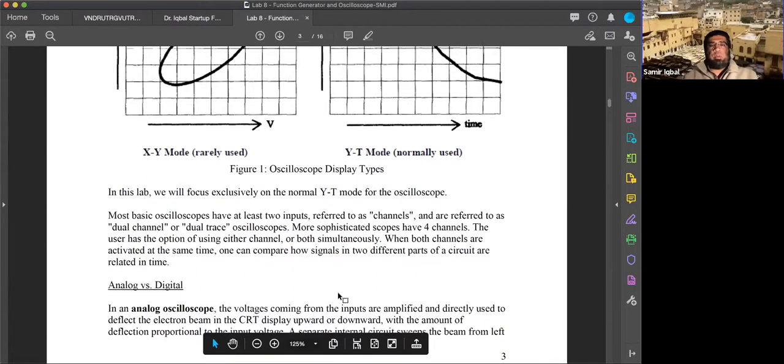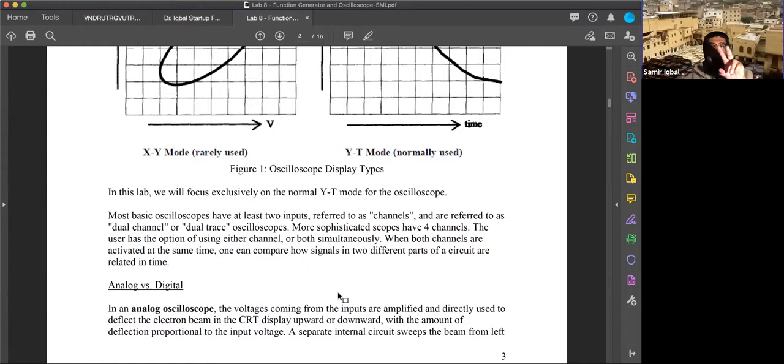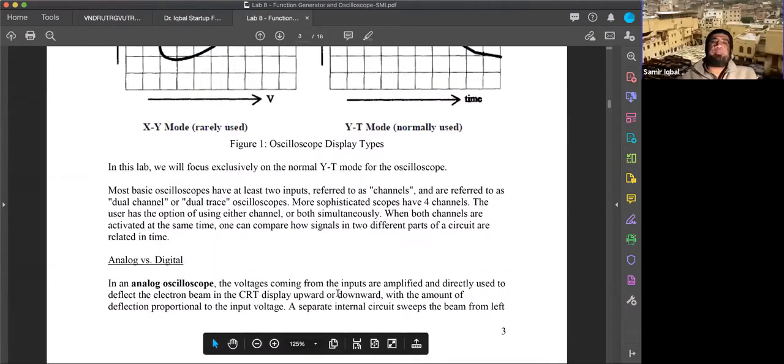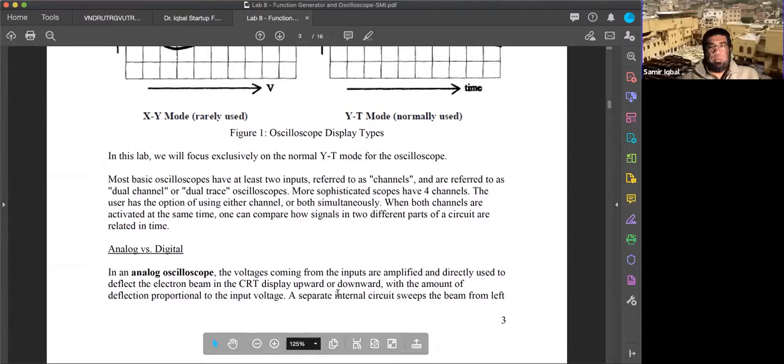All right, so we use two inputs. We use one signal with two cables, and another signal with two cables. So those two cables make one channel, the other two make two channels. So we can input two channels to the oscilloscope. The simple idea is that you may want to compare two signals, the input signal versus the signal at any given point in your circuit. So then you can trace those two signals and see the difference between them. Bigger, expensive scopes would have more channels as well.